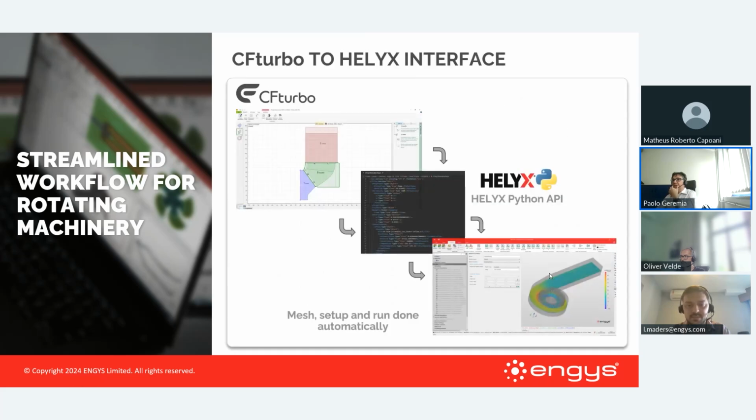And today we are going to talk about our CFturbo to Helix interface that we developed together with the development team of CFturbo. This is based on a Python API, which we provide in Helix. And this basically allows you to take the model created in CFturbo and automatically create the mesh, set up, and run in a row using a specific sequence. And this is what we are going to talk about today.